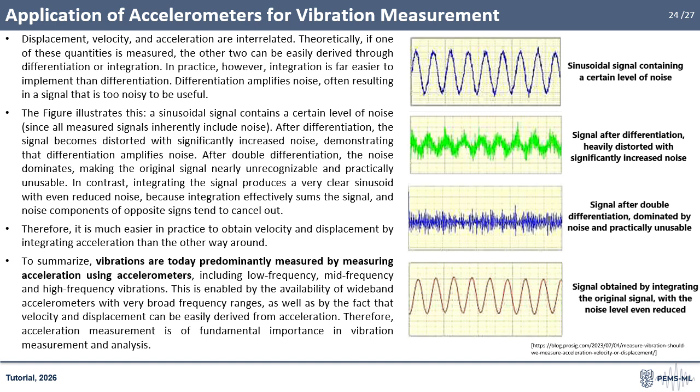Today, vibrations at all frequencies, low, medium, and high, are mostly measured using accelerometers. Wideband accelerometers make this possible, and since velocity and displacement can be derived from acceleration, measuring acceleration is fundamental for vibration analysis.